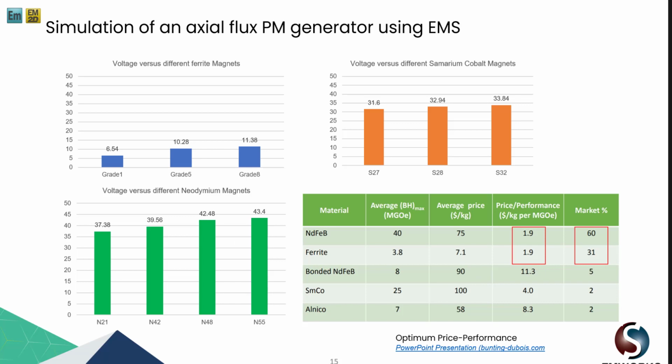So to improve the efficiency and the power, designers add more cores while using a compact structure. In this case, ferrite magnets can be used since they are lighter and cheaper. So we can have a machine with more poles and less weight, but deliver the same or even higher power compared to neodymium magnets.